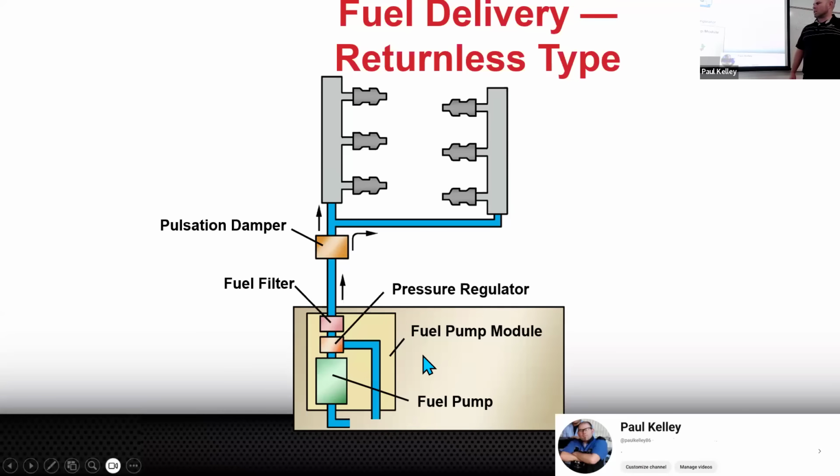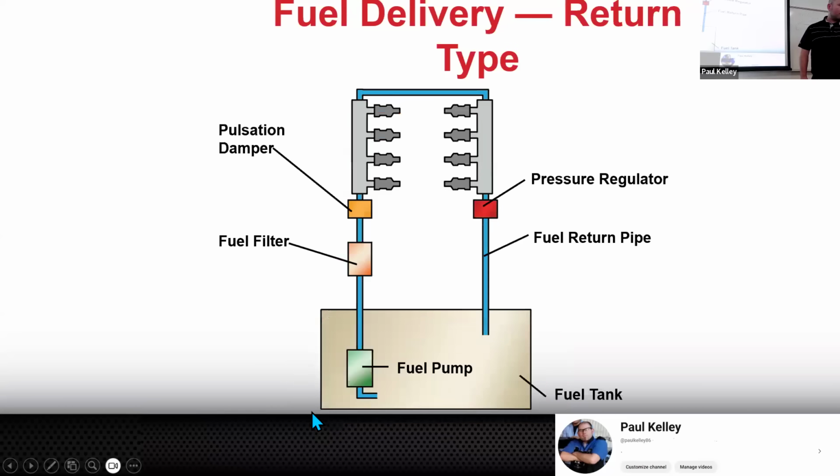So we've moved the fuel pressure regulator into the fuel pump module, which is not the control module, but the fuel pump sending unit. We'll call it the module now because it's together. It has the regulator too. And then it's going to leave the fuel pump and the tank and go, wait a minute, fuel filter? What the heck is that? Now they're putting the fuel filter in the fuel pump module. A lot of times it's actually down here as part of the sock, right? So back here, you could do your fuel filter. It was on the fuel rail.